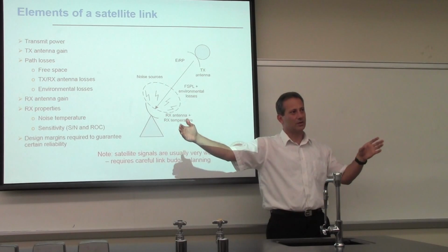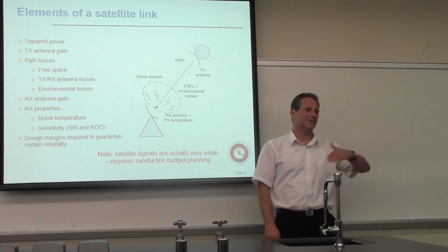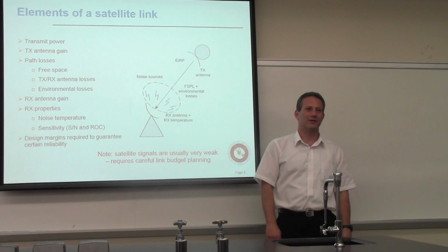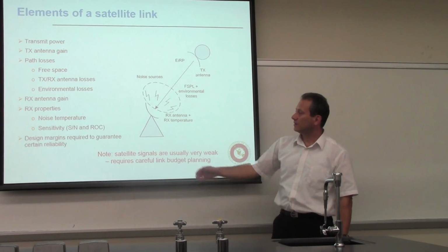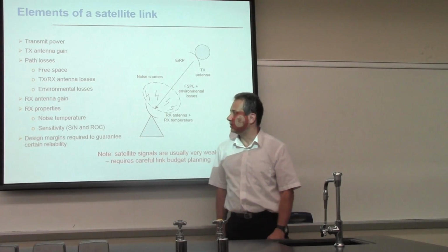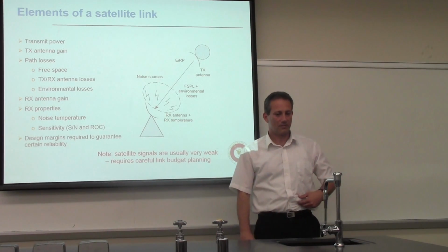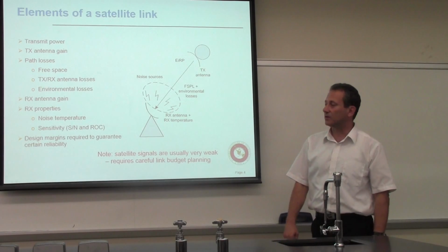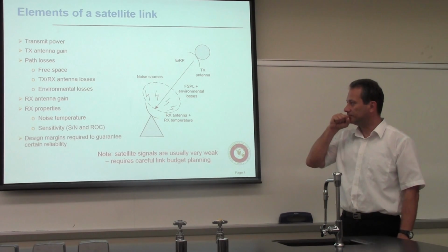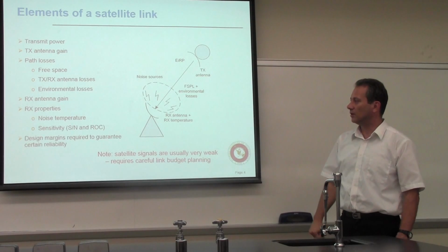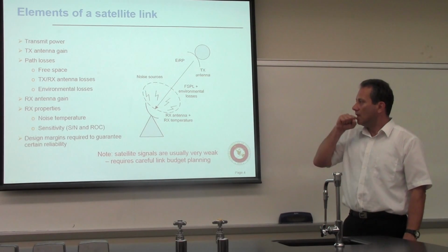Ultimately, you're going to reach the thermal noise, if you're lucky, right? A lot of times you end up finding interference and other signals that are present there. The thing that you need to know is what signal to noise ratio you need to provide so that the equipment operates within the proper specifications.